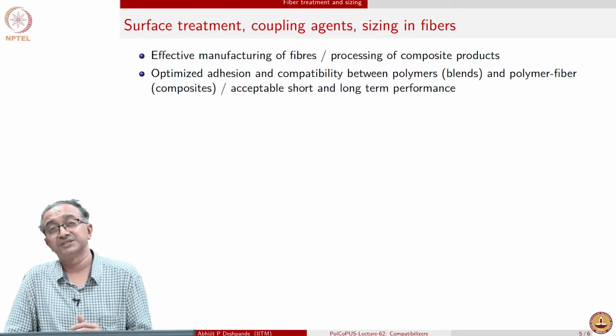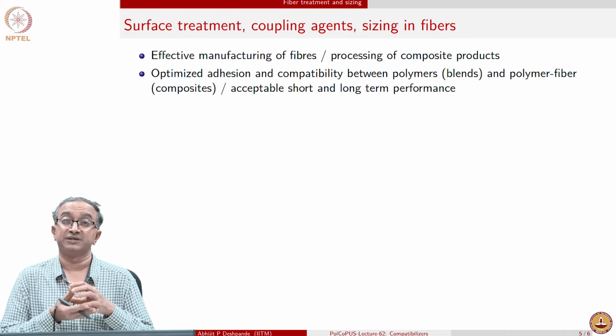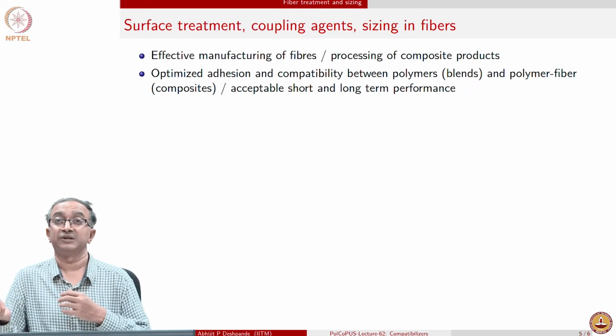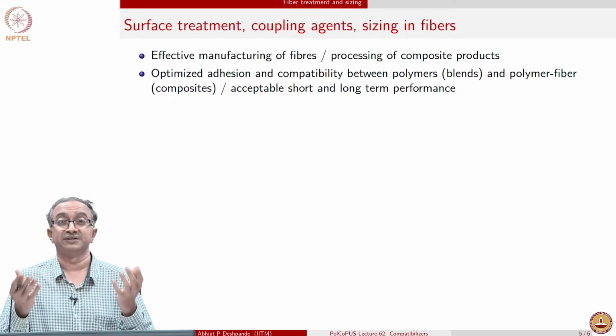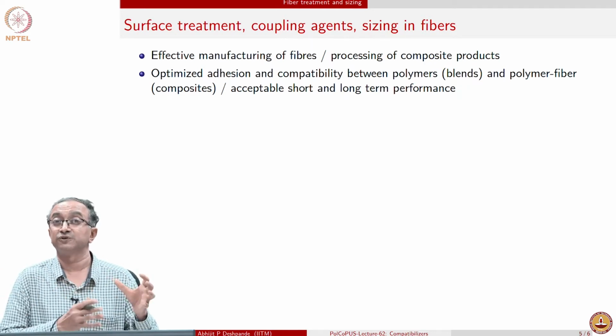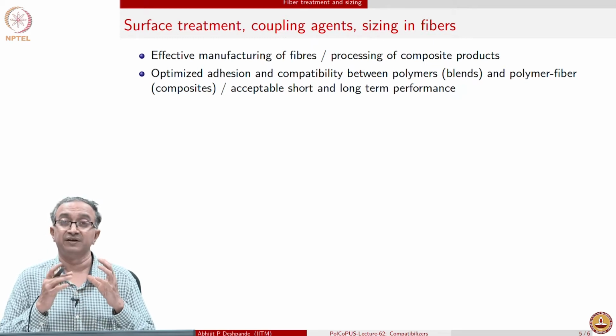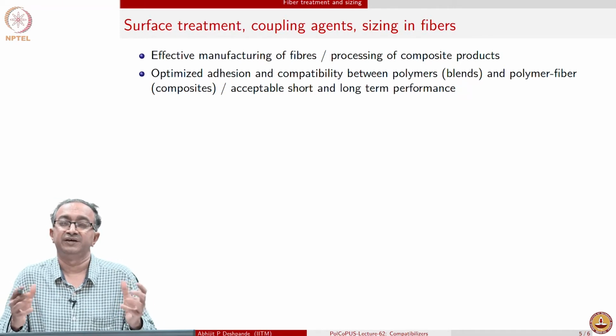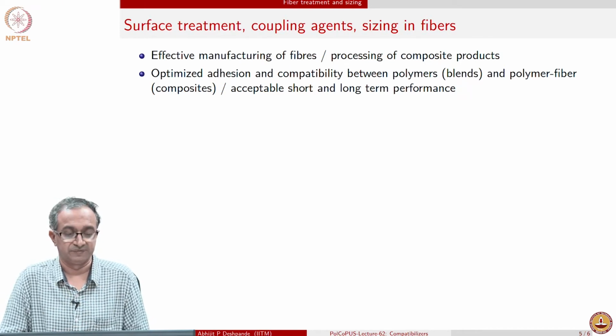As far as composites are concerned, we now have a fiber surface which could be glass or Kevlar, and then a matrix surface which could be epoxy or nylon or polyester or bismaleimide, as we discussed, related to the aerospace applications. So, we have a plethora of fibers available and lots of polymers which can be incorporated in a polymer composite.